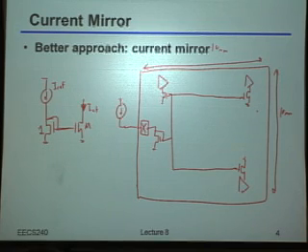Go ahead. With the layout being all over the place, they're definitely not very well matched. Okay. So you said those devices are not really close to each other. So the devices themselves may not be very well matched. That's kind of like saying the VTs may not be the same. That's absolutely correct. Yeah? You have really big wire parasitics, so you'll have drop across the wire, which sort of defeats the purpose of having these two.